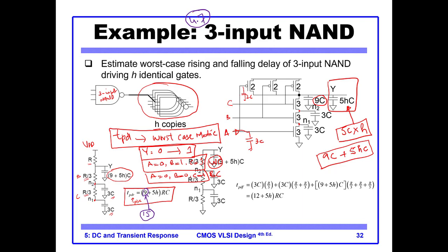In the solved example, it is 15 instead of 9 here, and how it comes out 15 is interesting, because if we look at the circuit, the output capacitor is charged only through the resistance R. That's why here we have R and not something like R plus R by 3 plus R by 3. Because it is only charged through R.